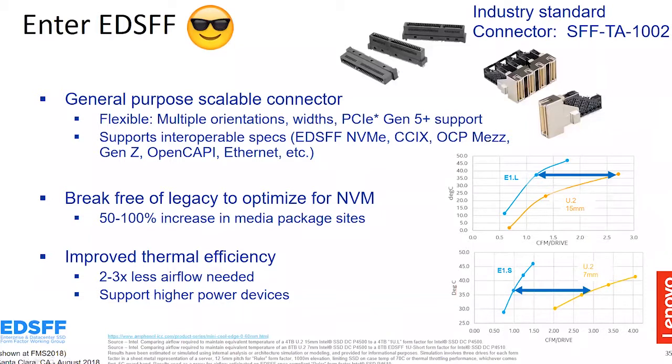And so you see up here on the top right, this is a right angle orthogonal EDSFF connector version. And the nice thing about this, we still have this vertical version here in the middle, but if you look at the top right here, this orthogonal one stands up straight. And so we've standardized this, so now you can actually have a horizontal backplane instead of a vertical backplane. And so with that, you don't block the airflow. You can plug the drives right in, hot plug into this. All the EDSFF drives are hot plug capable, and you plug it in, and it just goes right into the backplane. So this could actually even be a single board, even without a backplane, with the same motherboard that you can plug this into.